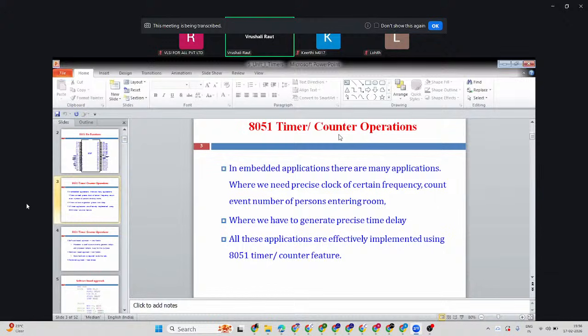So this can be the project. In programming, I am using the counter. I am setting the counter and doing that project. Externally, what will be required? That sensor will be required, which gives a pulse when an obstruction comes. You can search for that type of sensor. A number of sensors like that are available. Right? So that is the counter part. Now think of the other part. I have to use a timer.